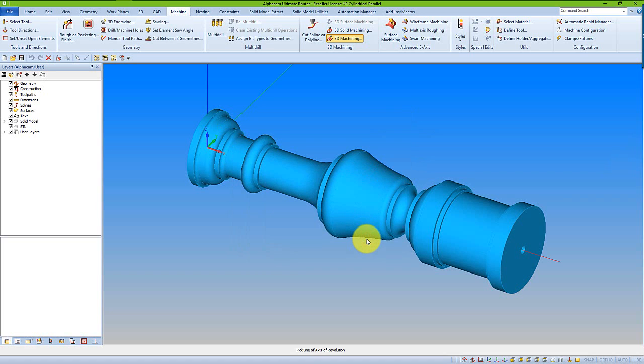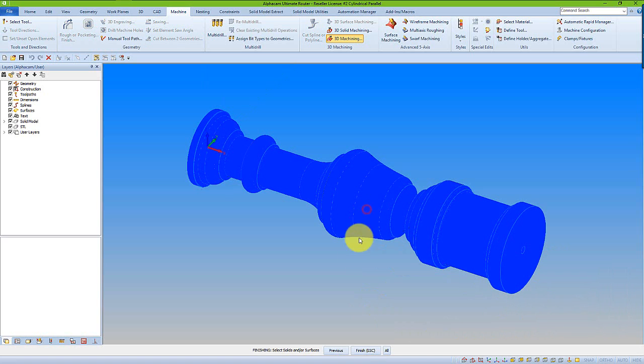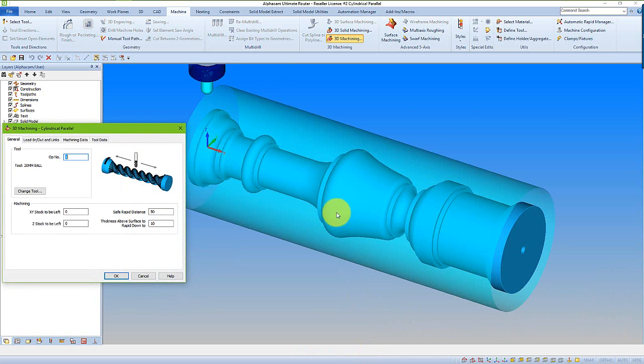So the first thing we have to do is pick a line of axis of revolution. It's going to be straight down the centre of the part. This is the axis that the tool will rotate around. We now pick the solid that we're going to look at, and we can now see the extents visualization. So we have our Z levels and things. I'm happy with that.